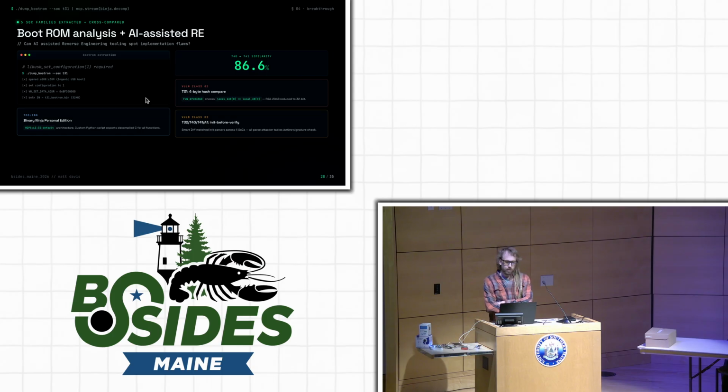What if I told you that you can implement secure boot and possibly do it incorrectly? Well, in order to determine whether or not you did it correctly, you need to be able to extract from the SoC what is known as the boot ROM. The boot ROM is infused in the chip at the time of manufacture. It contains code, and it can't be modified. It's different from flash ROM. It's just burnt into the chip.